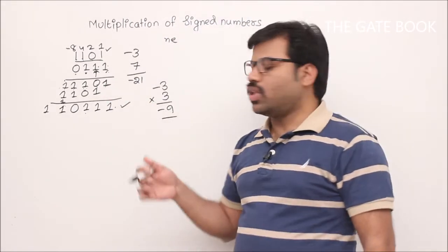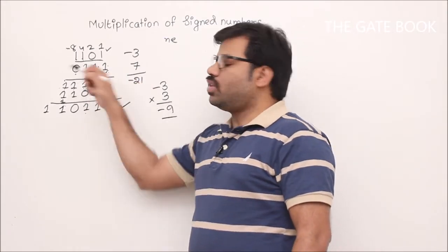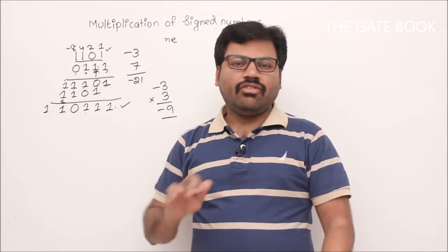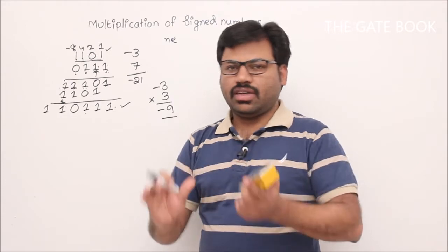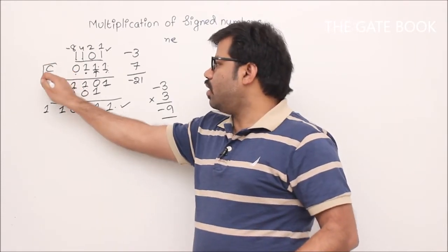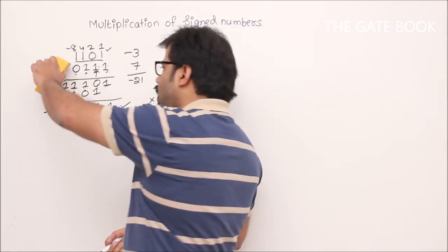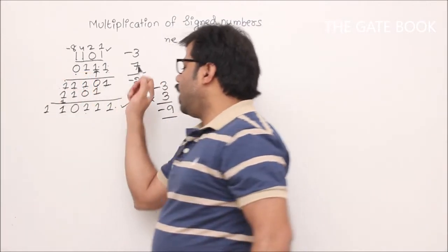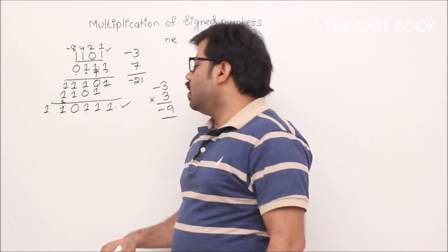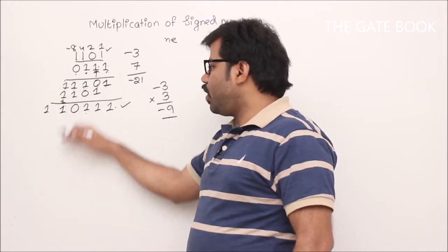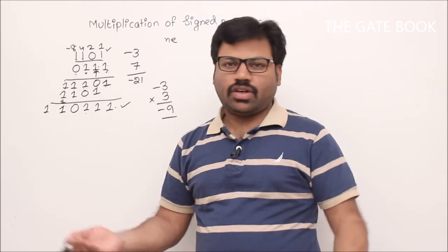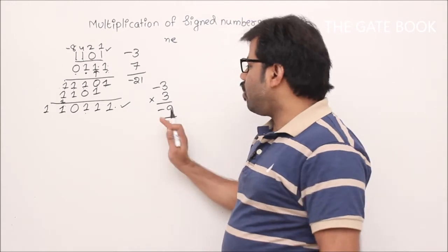While shifting to the right side, we have to extend. That means the last bit, the carry bit, you remember that carry bit, should get 1. That is one thing. This is called sign extension, so simply extend the sign. Second thing, everything is correct. Simply do unsigned number addition. It will work for signed numbers also. So far I got minus 9.